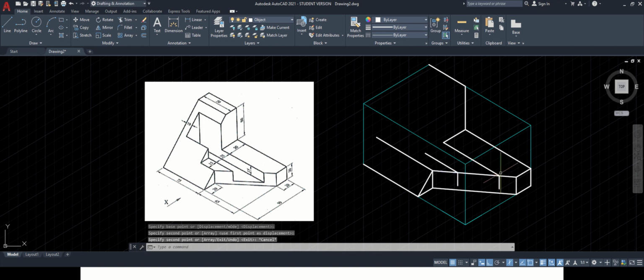So now this portion is not visible, so I will take help of trim command and trim that portion. Now these 2 points are to be joined with line command. So go to line command, select first point, select second point. We have completed that. Now next thing is this line is visible to us. Again we can make use of copy command. Select this line, enter. From here paste just below that and say escape. For now I do not know up to which distance this line is to be extended. So I will keep it as it is.